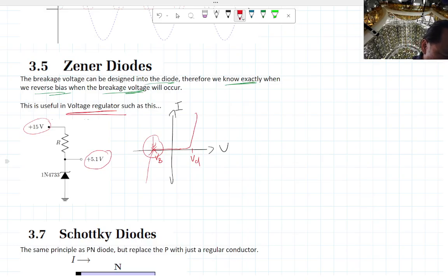What you do is you connect this to a resistor and through this 1N4733 diode, which has a breakdown voltage of 5.1 volts. If the voltage gets above, let's say, 5.2, this becomes a short, and it's basically running the current to ground. Actually, it turns to 5.1, right?